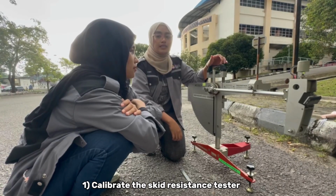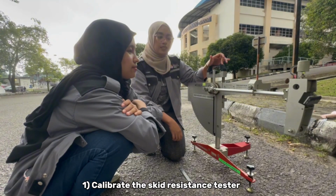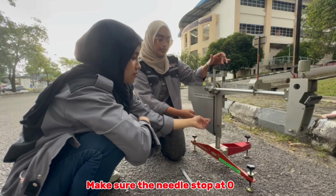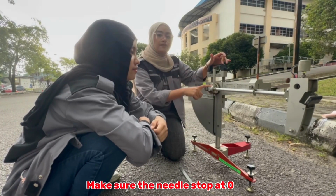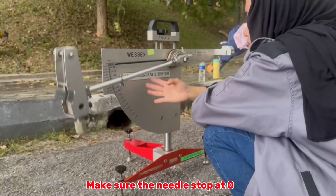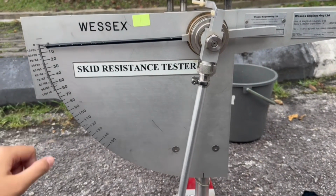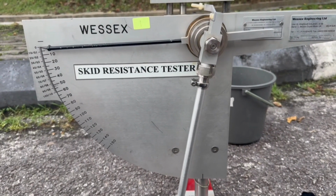Before we conduct the experiment, we need to make sure that the skid resistance tester is calibrated so that the needle is set to 0 when the pendulum is released. As you can see here, the needle has touched the 0, so we have successfully calibrated the skid resistance tester.